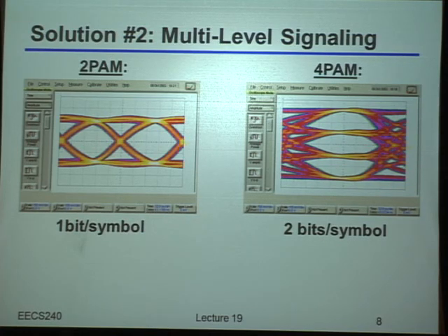And so the way you do that is actually conceptually simple and very similar to what we've talked about in the past. So if you think about it, so far everything we've been looking at has been a very, very simple digital communication system. It said we can always only send 2 levels, either +1 or -1. By the way, that's what's called a so-called 2-PAM system. PAM just stands for pulse amplitude modulation. So the trick here is because we're only sending those 2 levels, at every symbol time, we can only send one bit of information.